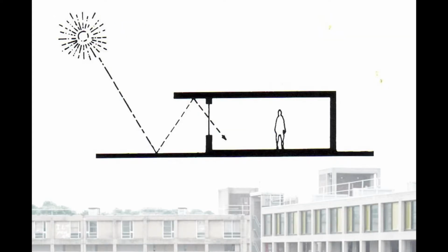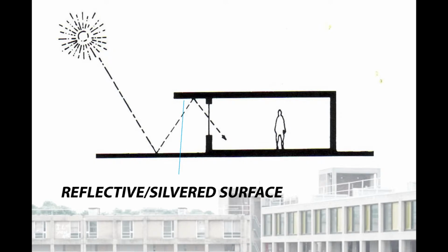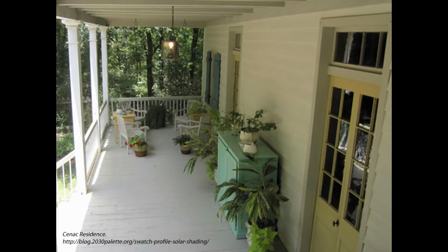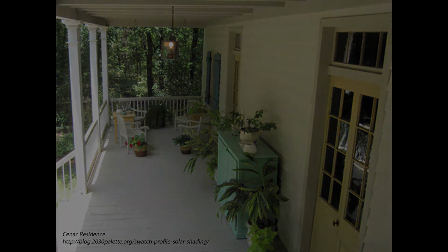If overhangs need to be oversized, i.e. for a canopy or sheltered walkway, it is best to have the underside as a reflective material so that sunlight can still be reflected back into the interiors. In very hot climates or in countries close to the equator, it is best to shade the entire solar facade.